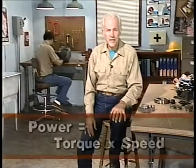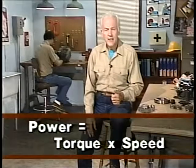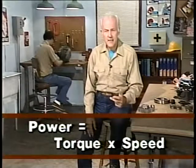Well, so far we've looked at how speed can be changed across a gear set, and we've seen how this change can be described by using a gear ratio. These ratios can be used to help determine the speed of rotation of a gear set if the input or output speed of the gear set is known. Now remember, we said that the reason gears are used in machinery is to transmit power, and the way in which gears transmit power can be described using the equation power equals torque times speed.